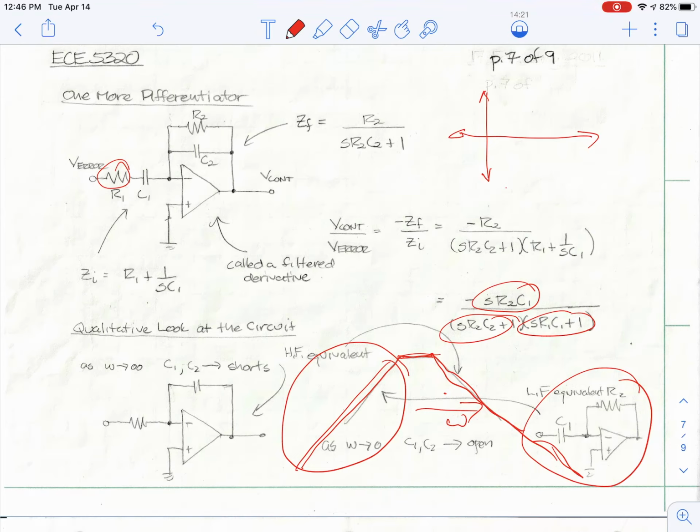There are ways to do this for sequences. If I have a digital sequence of data and I have the whole sequence, I can filter it digitally forward and then filter the sequence digitally backwards, eliminating all phase shift, and I can actually take a derivative without too much problem. But you have to have the entire sequence, which means this is useless for control.